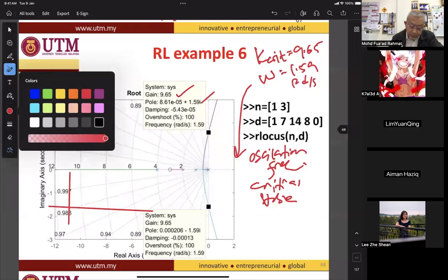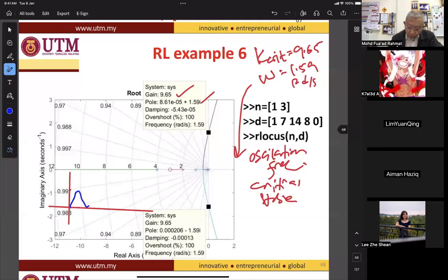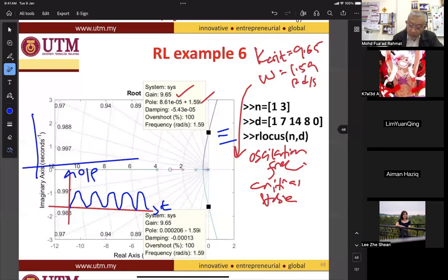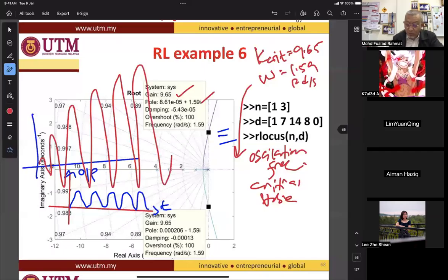Okay, it is an oscillation. Okay, time versus output. But for the negative part, okay, when zeta is a negative damp, the response will be dangerous. Okay, it is bigger when time goes towards infinity. So this kind of response is unstable.